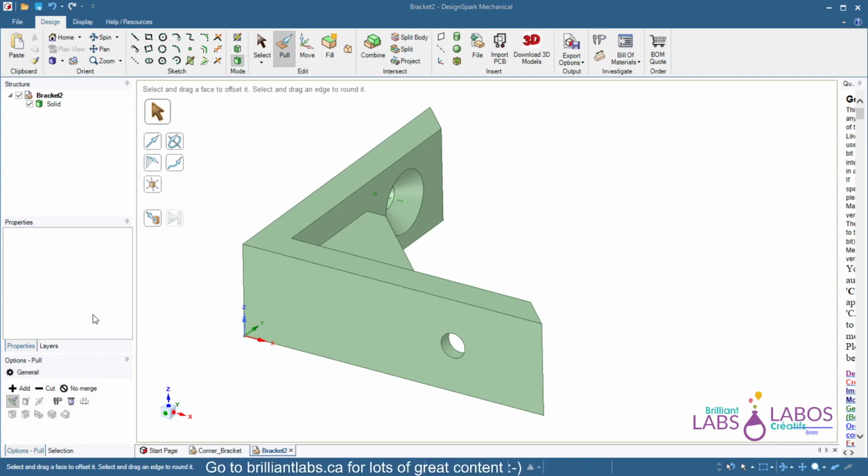But the one we often use, and we're going to use most often in 3D design, is STL. Those are also popular, but STL is the most popular one. And this is why I suggest that you use Save As, because another way of doing exactly the same thing is Export here. Export file to various formats. It's really using the Save As command.